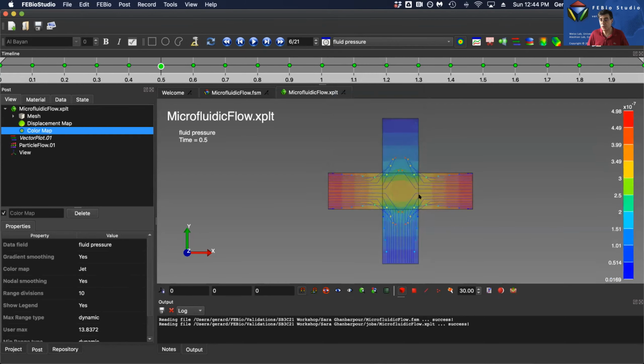So you need to solve that problem that I solved for you, but for whatever pressure you're going to apply. I can share that model with you, just email me. Then you get the pressure from this and you apply that pressure field on a particle that's just an elastic analysis, subject it to a pressure that's non-uniform around it, and you figure out how much it deforms.